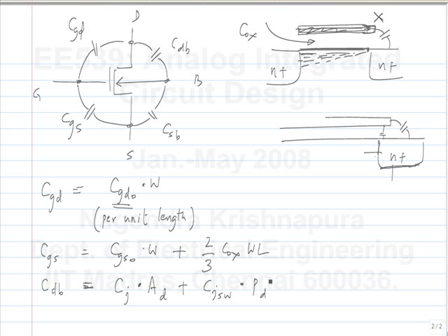Okay, if you know the syntax for MOSFET and SPICE, you have to specify the width and length and the number of fingers as well as the perimeter of the drain and the area of the drain, perimeter of the source, area of the source. The reason you need all of this is to calculate the parasitic capacitances. Okay.